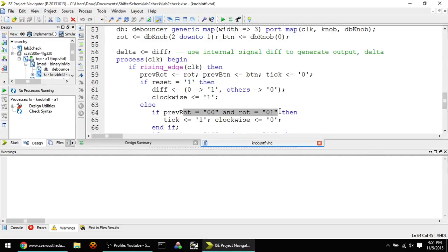Variables. If I set a variable, that value is in there right away, right? If I set a signal, that signal does not get updated until after everything else, at the very end of the process. So that's why saying something like this is okay. We're actually just queuing this up to happen in the future. Does that make sense? I know it's confusing. It's a little odd, especially compared to other programming languages, but that's how it works. That's how we can write something like that and not sound totally crazy.